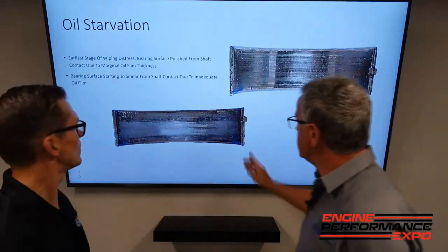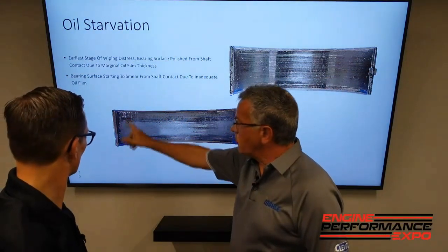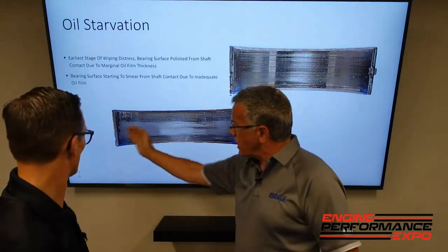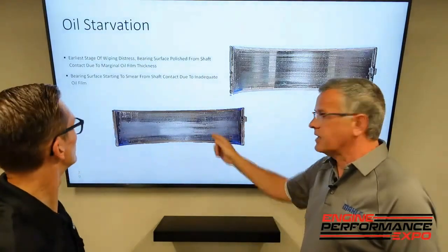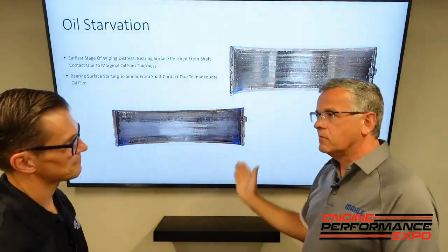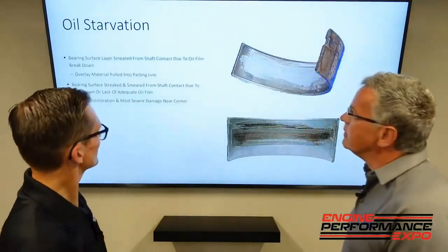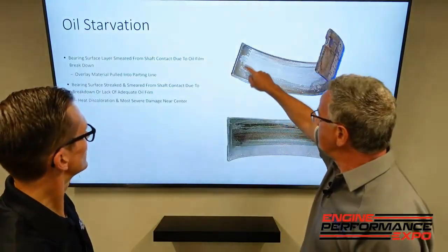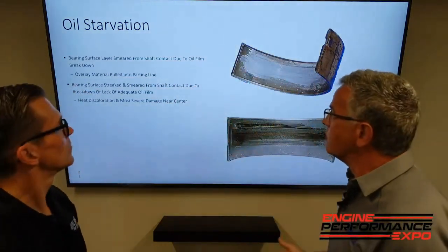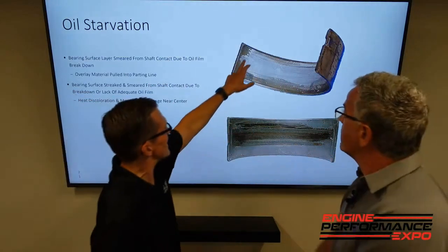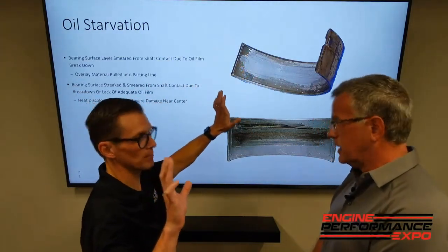You can tell this bearing is getting hot, and if you look, you can actually see on the bore relief, as I talked about, it's moving metal. It's always moving over. It is smearing it over. Next thing that's going to happen, it's going to get black, get down to the substrate, close, spin, rod out the side. Again, oil starvation, another prime example of material transfer. It's just smearing it over. Because if you see anything in that relief area, that's a big red flag. That's a giant problem.